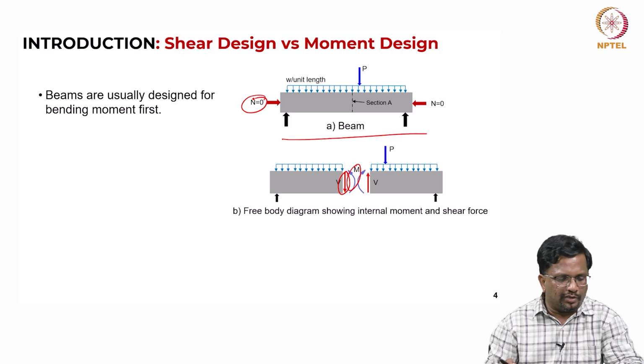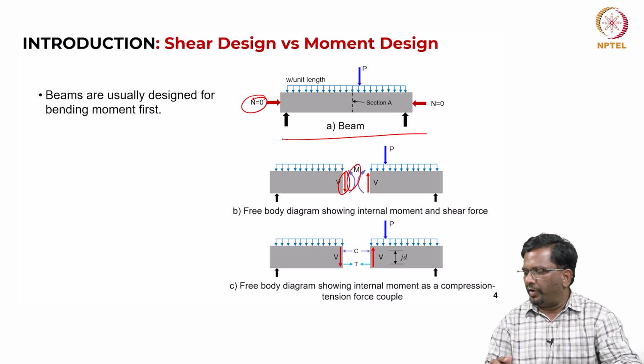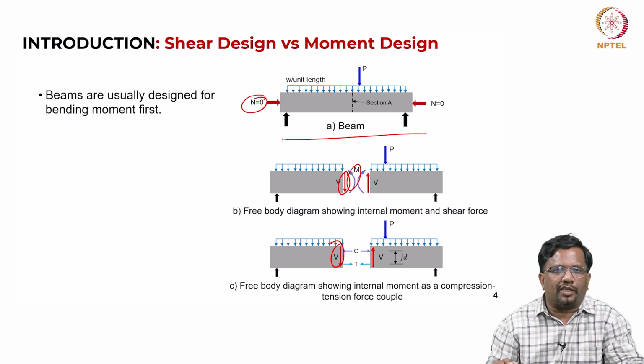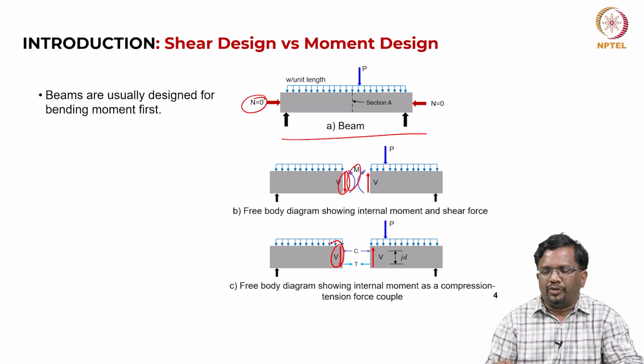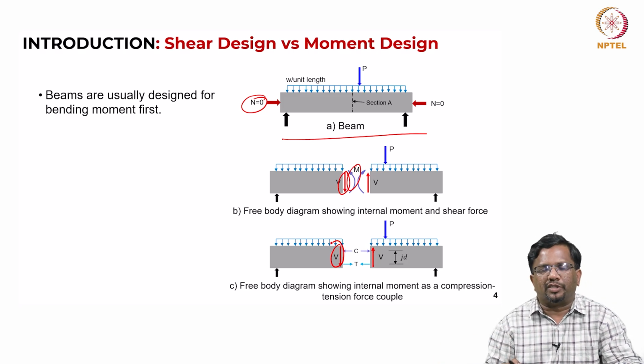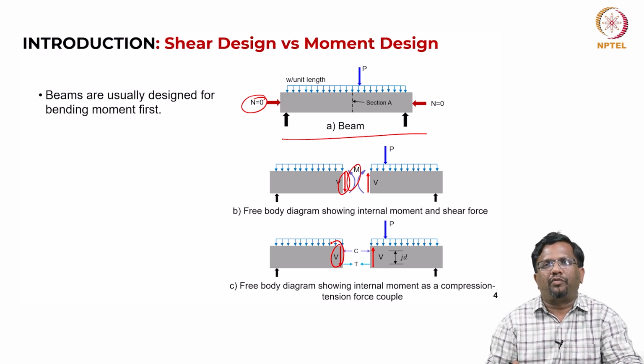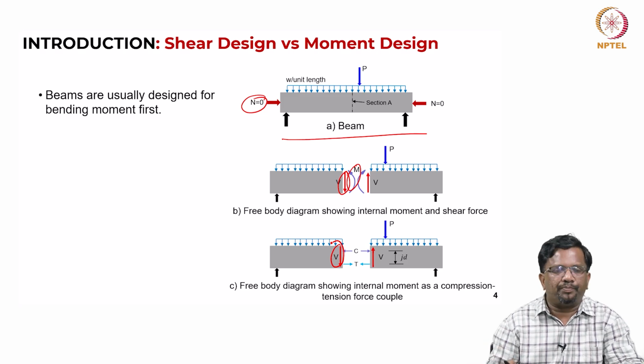For the bending moment, first we come up with the reinforcement requirements, typically the flexural reinforcement, the longitudinal bars are designed for. However, in addition to that, you also have shear acting in this cross section. So, we need to make sure that the section that is designed is also going to be sufficiently strong for resisting the internal shear force that is being developed.